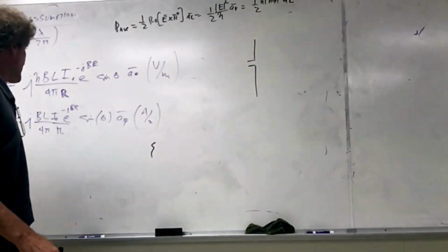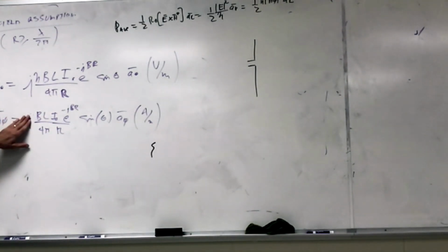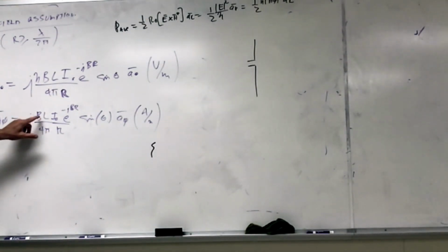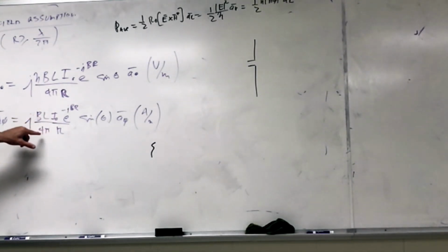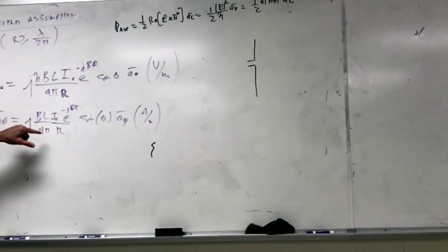The H field might be easier because if I look at this and square it, magnitude squared, get rid of the j, then I got beta, which is 2 pi over lambda, times L, times I naught divided by 4 pi, so 2 pi over 4 pi is simply 1/2, right? Then you have, were you missing the intrinsic on that? Where?